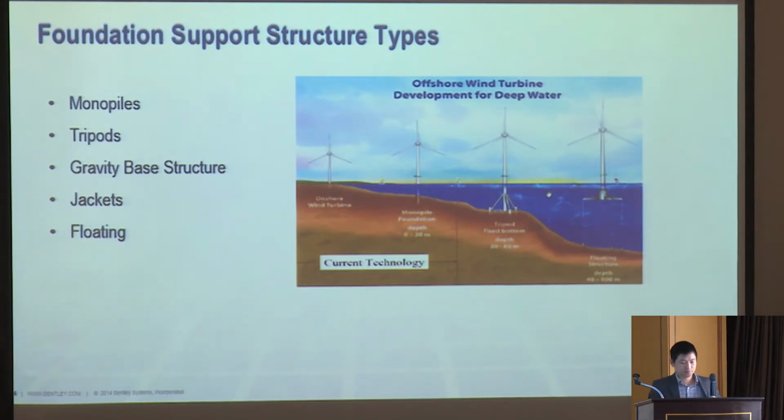And the choice of the turbine foundation depends on the following factors: the water depth, the soil bed conditions, the environmental loadings, the construction methodology, and the availability of installation vessels, as well as cost.